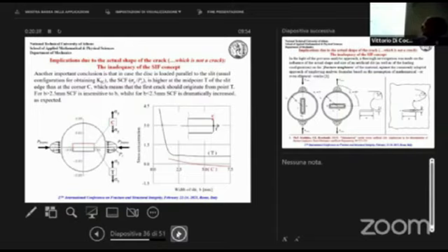So we tried to plot the stress components in terms of the stress concentration and not the stress intensity factor. And what was very important also is that it strongly depends on the width of the notch that we machine. And also, there are differences on the stress concentration at various points of the crack notch, of the crown of the notch.